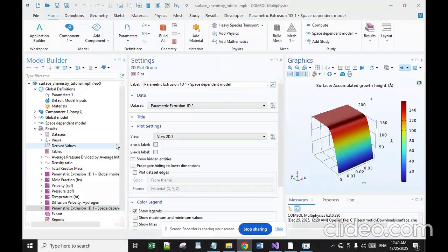The next one is hot filament CVD, also known as catalytic CVD or, more commonly, initiated CVD. This process uses a hot filament to chemically decompose the source gases. The filament temperature and substrate temperature thus are independently controlled, allowing colder temperatures for better adsorption rates at the substrate and higher temperatures necessary for the decomposition of precursors to free radicals at the filament.